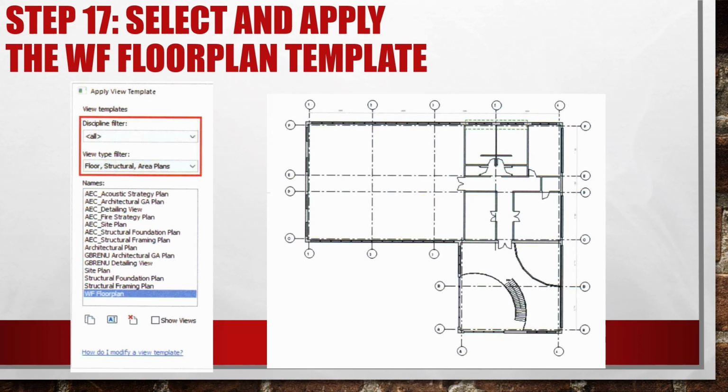Note, the first floor plan now displays the furniture as hidden, and the previously invisible dimensions are visible and shown in halftone, matching the ground floor plan. The grids, however, have not turned red. This is because the adjustments to the dimensions and furniture were made by category, which is captured when creating a view template. In contrast, the grid modifications were made by element and therefore are not included in the template.